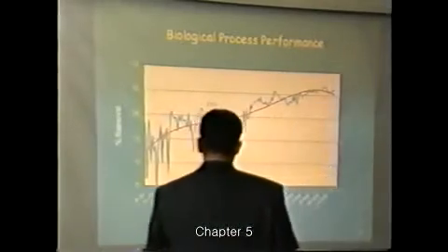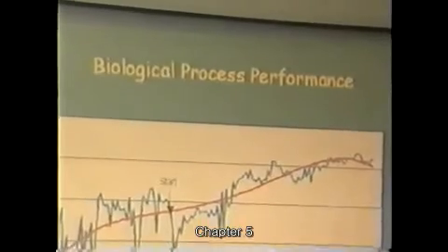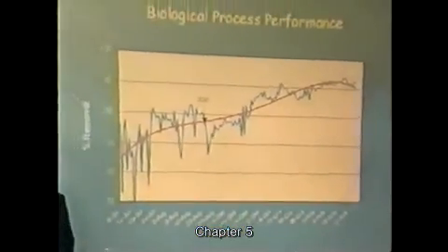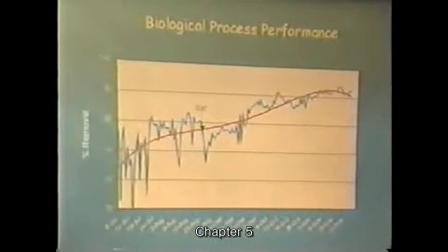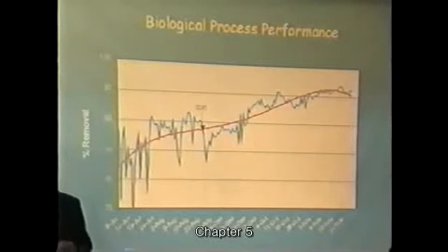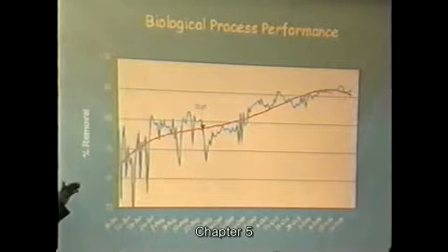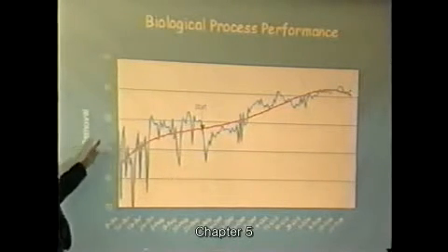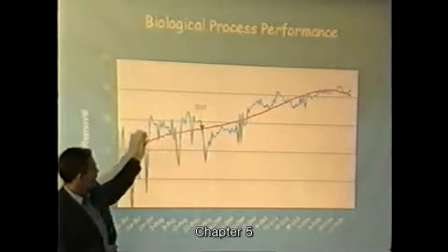This is the performance curve we got out of a little pilot plant we did with Sasol. Sasol is a big petrochemical company in South Africa, where they start off with a COD of approximately 20 to 30,000, and they had a typical performance of about 85 or 90%. Interestingly enough, they added micronutrients before we started.